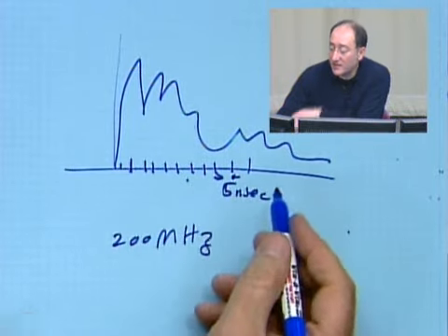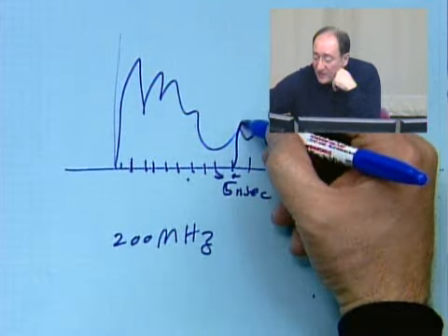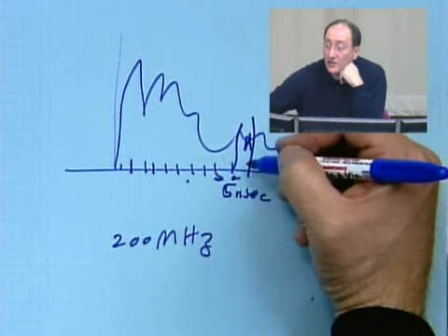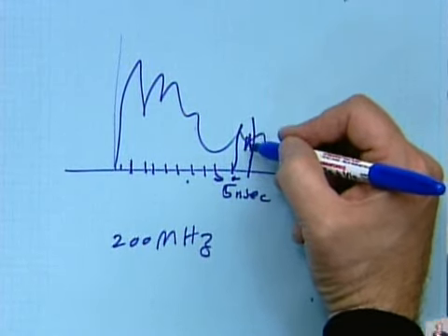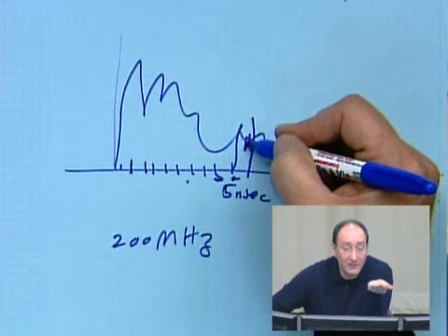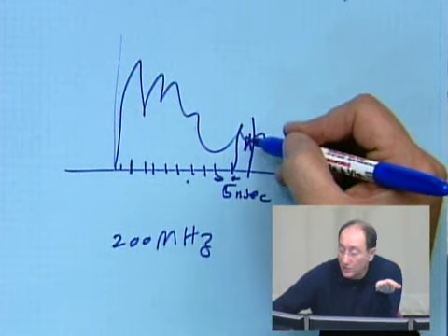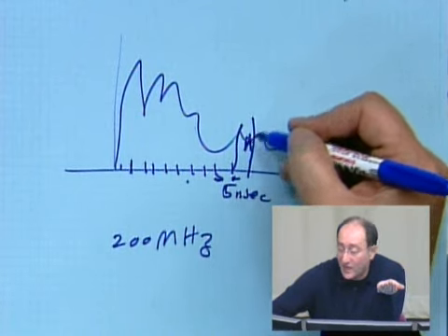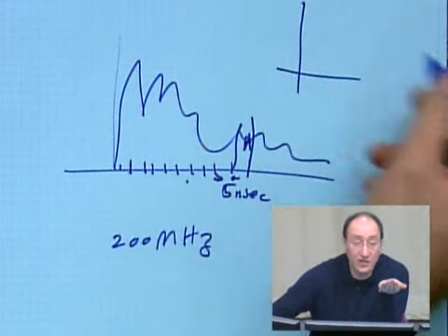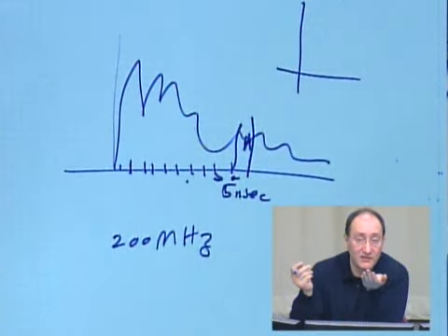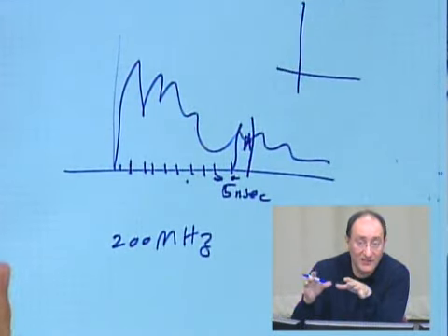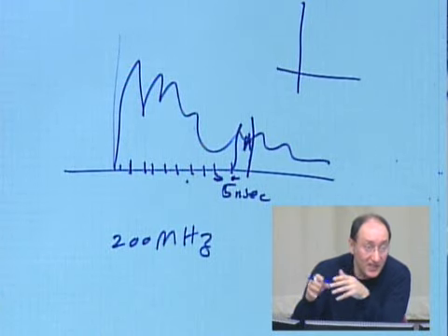In each bin, either I have a path or I don't have a path. If I have a path, this path has a certain amplitude. Then I get all of these amplitudes and I fit them to density functions. Saleh was not doing that. They were making the assumption that they are Rayleigh.